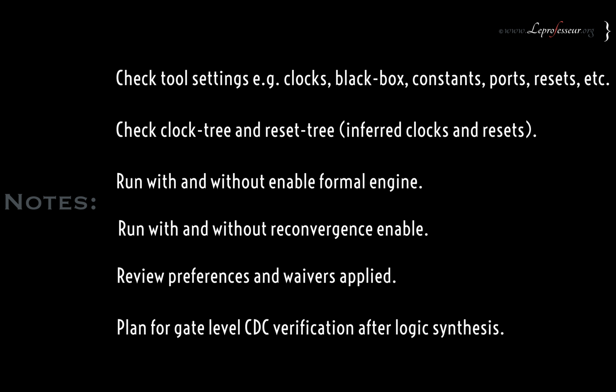A lot of chip ICs are screwed up because clock domain crossing issues are not being taken seriously by the designers or by the design leads. Plan in advance. It's very important that the CDC issues must be cleared before tape out of the chip.